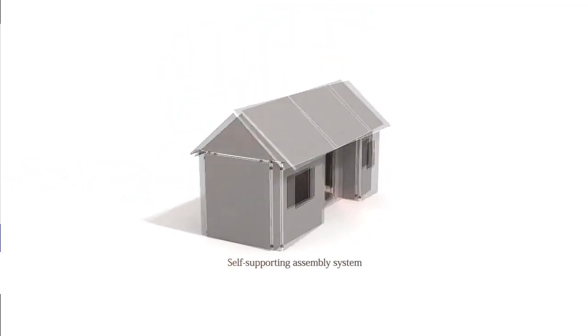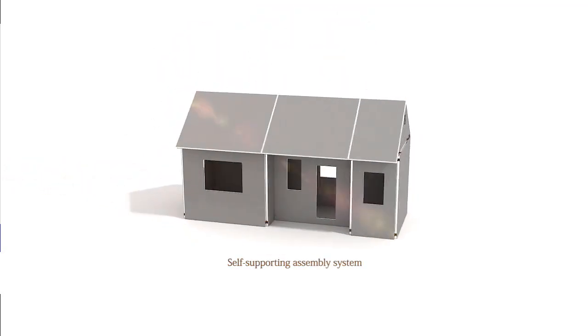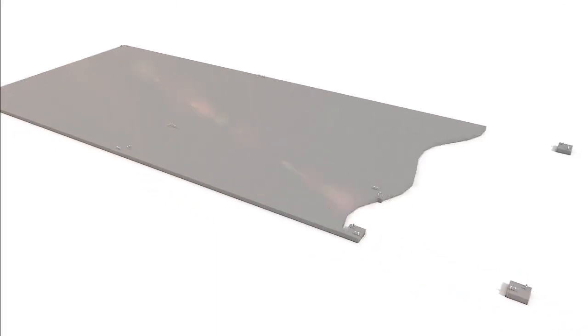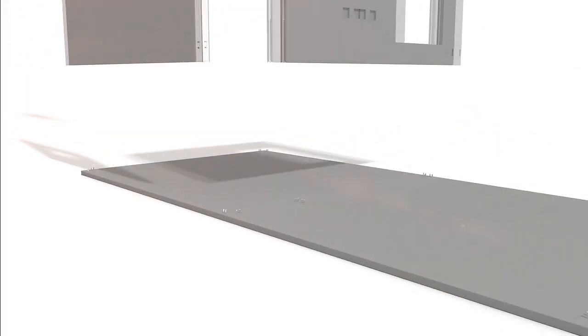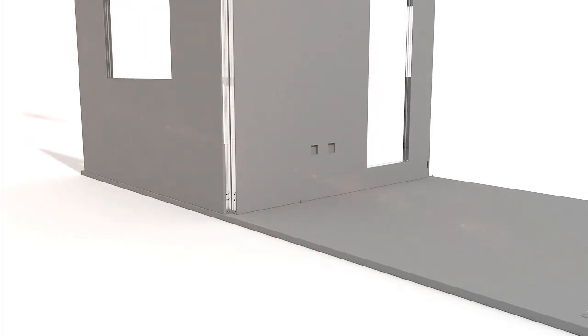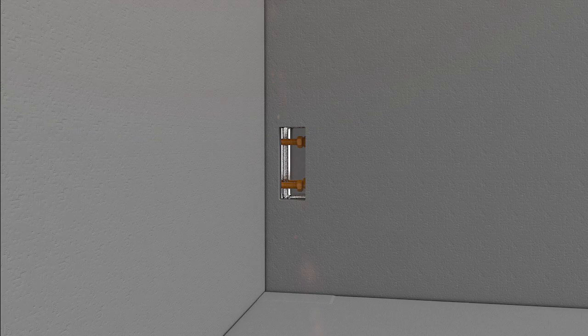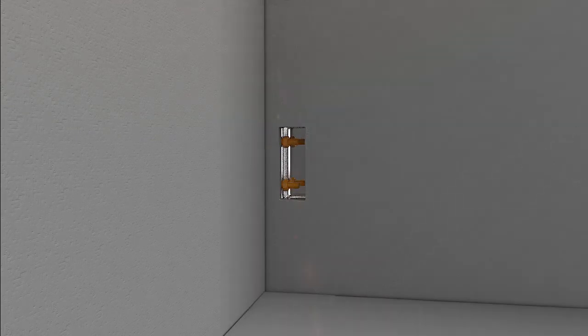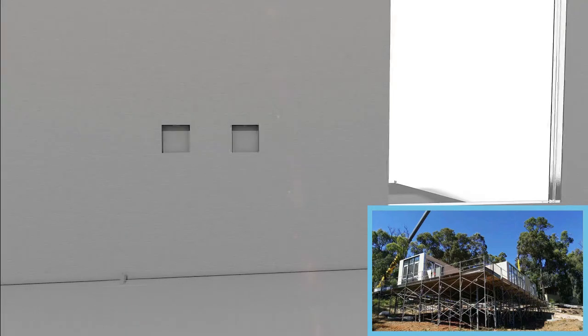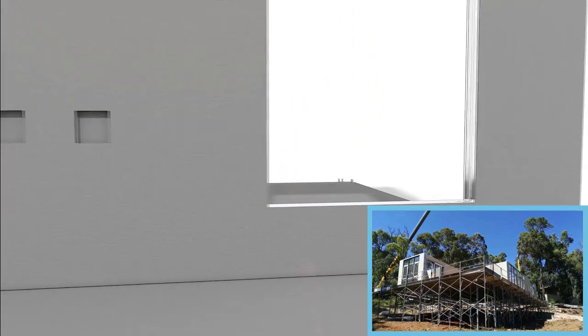A self-supporting assembly system is used on the low floors of new rural construction. Installation of the precast concrete floor and the pre-embedded parts. The design plate is installed to the relevant strutting piece, using bolts to connect neighboring wall plates. The pipes and holes are reserved before construction.